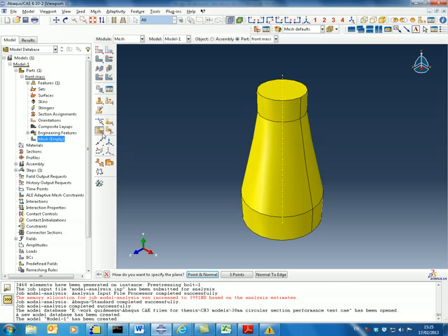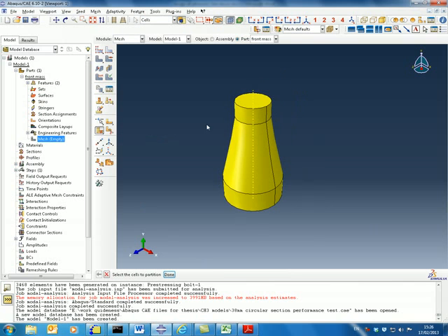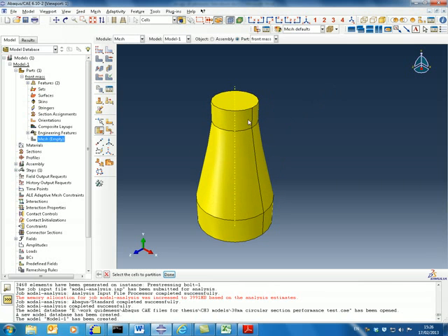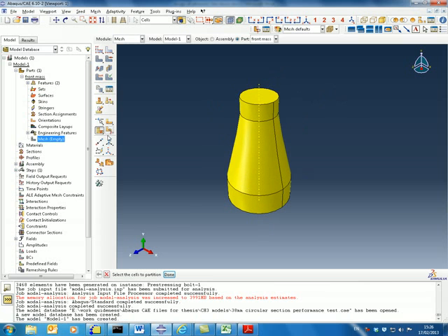So I'll use these techniques to convert my structure to accept the structured meshing technique. First I select point and normal. Select a point on the corner where the exponential decay started and select the central line, and you can see it's virtually separated into two parts, but in reality it's still one geometry. Again, I'll use it to split the base.